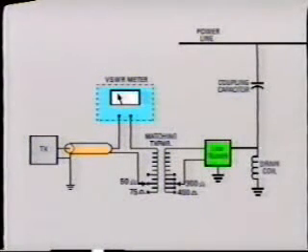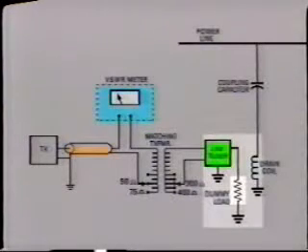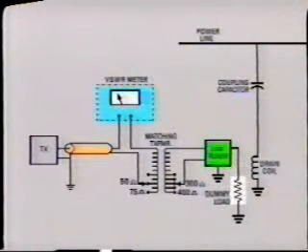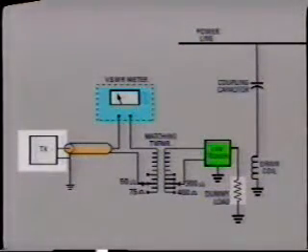This is not so easy where several transmitters are connected operating at different frequencies. One way of handling this is to connect the LMU into a dummy resistive load equal to the line impedance and adjust the impedance matching at the carrier equipment for each different frequency. Make sure you follow the manufacturer's instructions closely. There is an extremely wide range of equipment and a great variety of test procedures. One particular utility company test procedure is indicated in your workbook. Study this carefully, but make sure you follow your company's procedure when conducting this test.